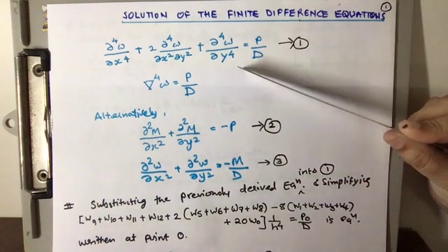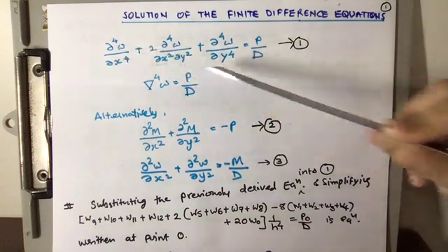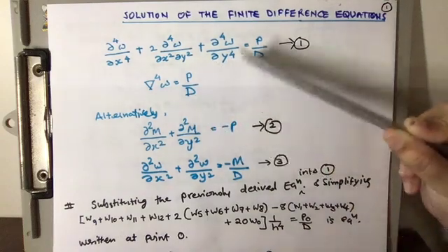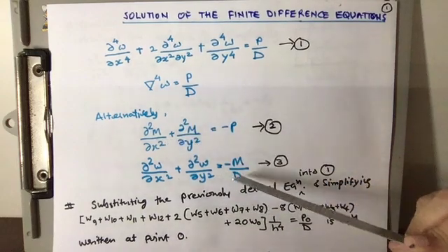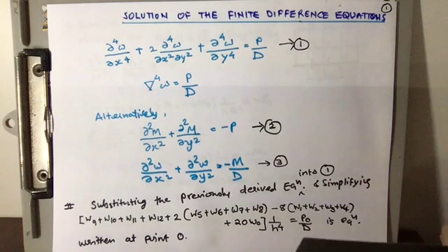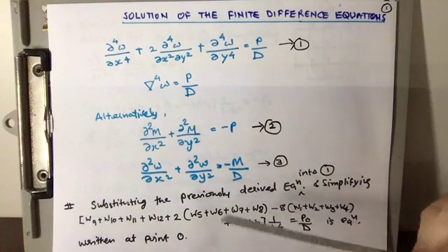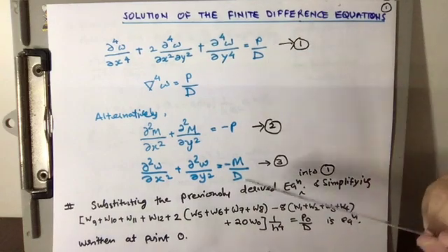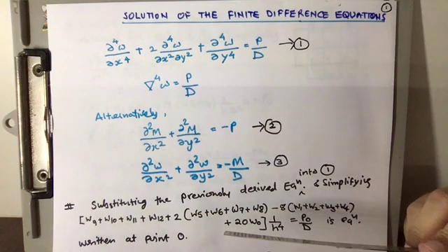fourth order governing differential equations, which describe the plate in bending, is written as equation 1. Alternatively, we have also seen that it can be replaced with two second order partial differential equations, in terms of moment and deflection, in terms of load and in terms of moment. Now, the finite difference equations that we have derived in our previous lectures, we are going to substitute into our equation 1, and then simplifying, we consider the same grid which we have taken earlier.